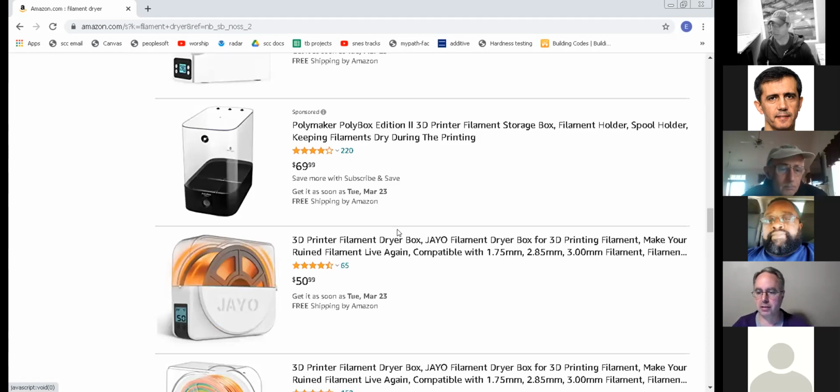While we're talking about filament, that brings up another good point that we work on with our technicians: why are my prints failing? Why is quality not that great? One of the things we have them test every now and then is filament diameter. They get out the digital calipers and take a strand and check it. Is it actually 1.75, or is it varying more than the slicer is accounting for? That will affect your print quality. Sometimes it gets thin, sometimes too thick, so we have them check the diameter. Now, it's not nearly the problem it used to be about 3 or 4 years ago when we were buying some of the lower cost filaments.